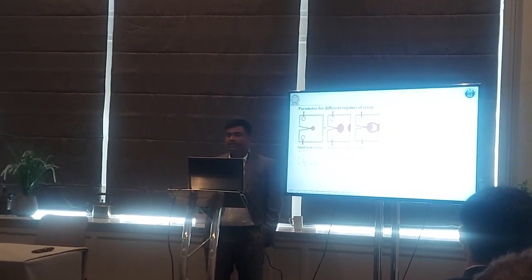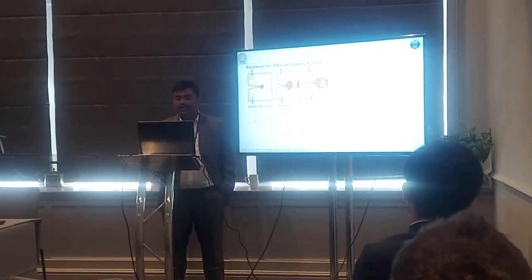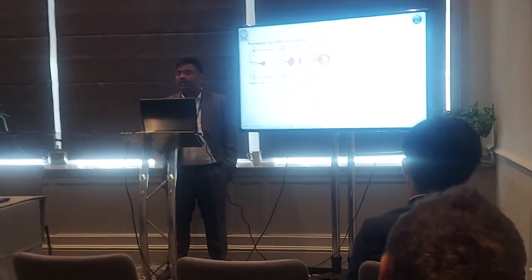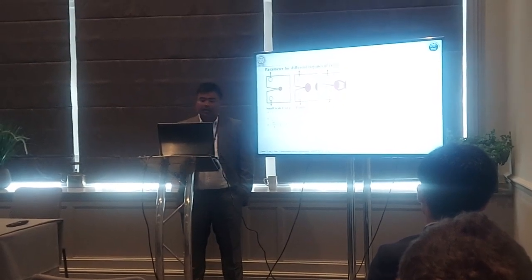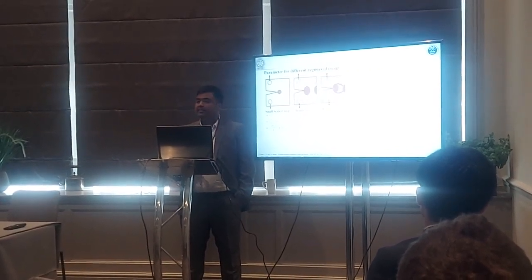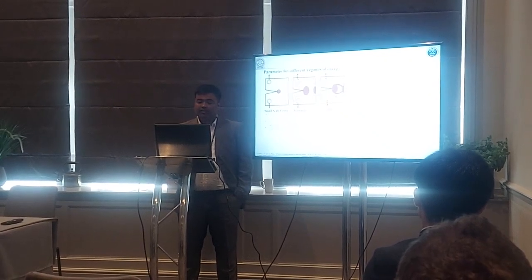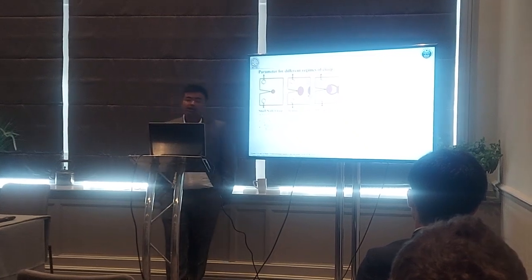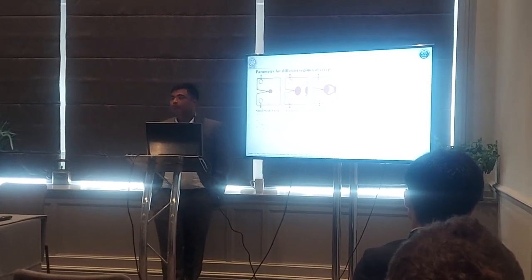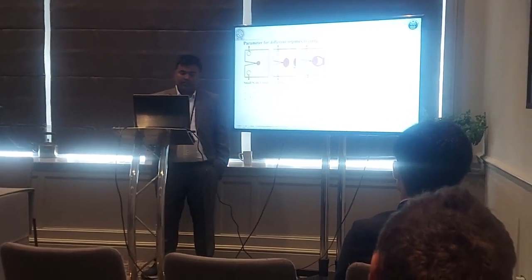This is called small scale creep. If the creep zone size covers the whole ligament length, this is called extensive creep condition. If the creep zone size is in between, this is called a transition creep condition. But the problem is how to find the stress and strain in the creeping condition at a crack tip.